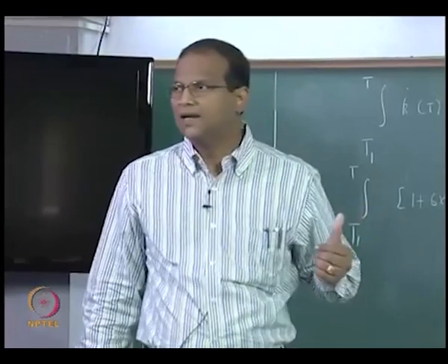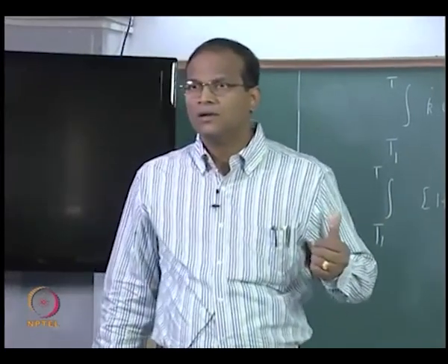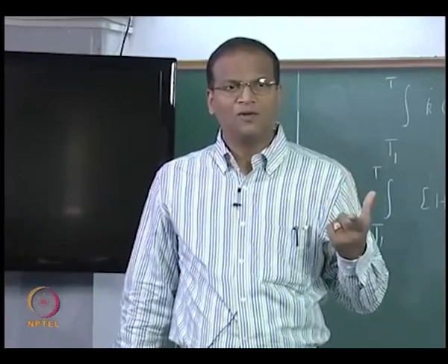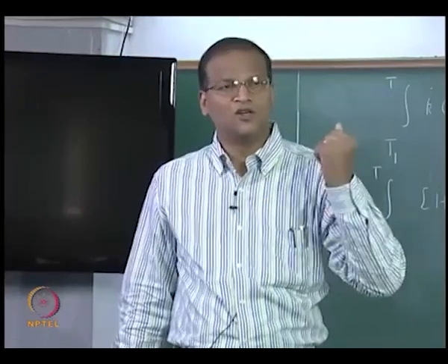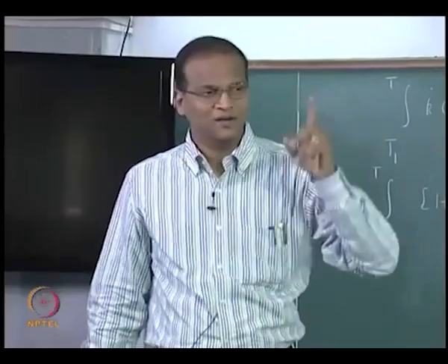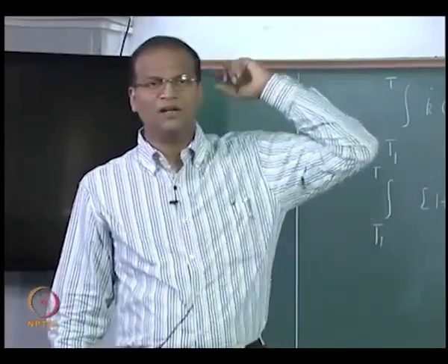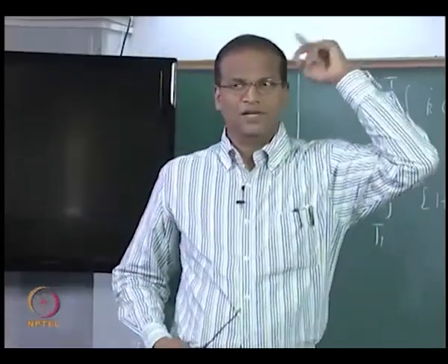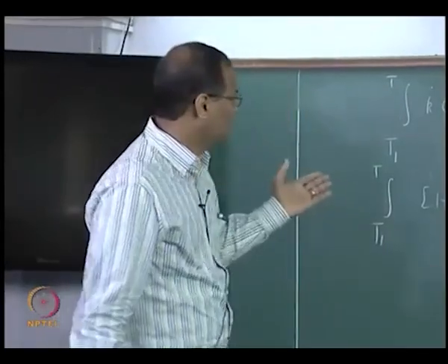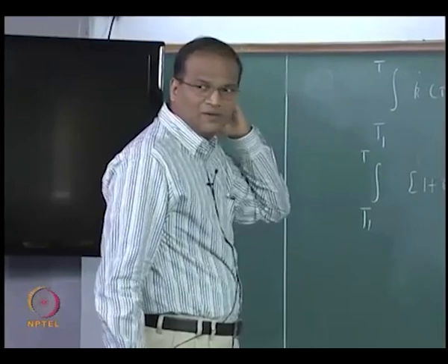You have to solve a quadratic. See, you have a very simple linear temperature distribution. Now, linear temperature distribution, constant thermal conductivity; linear thermal conductivity, quadratic temperature; quadratic thermal conductivity, cubic temperature. It will keep on, the difficulty level will escalate. Now, I hope to get a reasonable temperature, I do not know.